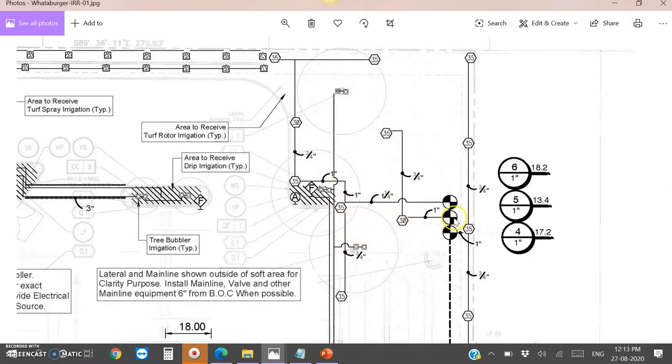And one more thing is, we cannot connect more than 25 psi, 25 flow GPM. That's why we have currently connected only 1, 2, 3, 4, 5, 6 rotors, because the restriction is only 22 GPM, so we cannot connect more than that. And in the next zone we just connected two rotors in a single zone.